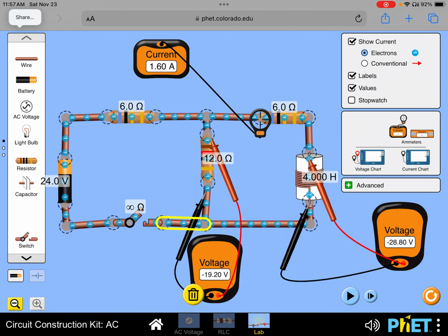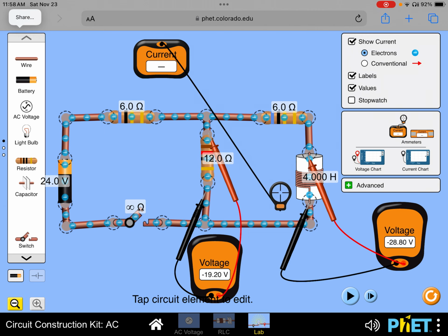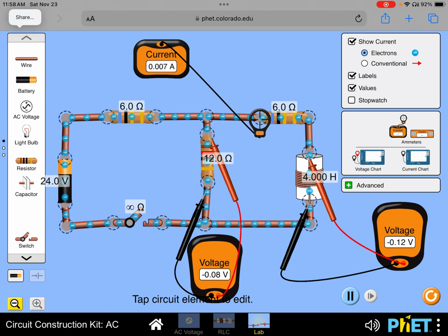The current instead, let's say on the first resistor, is nothing, 0, and the current in this left side of the circuit is 1.6. Of course, this value with the passing time will little by little go to 0 because there is no battery in this circuit. The inductor is like a little bit of a battery, keeping as much as it can the current around. Thank you.